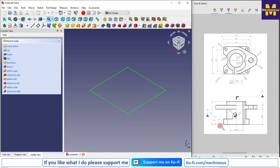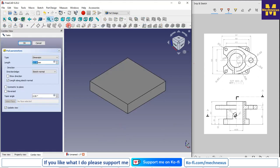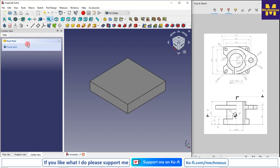The thickness of our base plate is 10 mm, so I will go with a pad, and here is 10 mm in one direction. Okay, now we will model the middle portion, which is a circular feature, and we can also see that our plate has the R12 cut. So let's first make the cut, because we have to apply this cut on our circular feature as well.